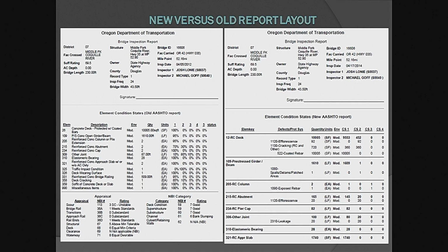So they're going to quantify for that 1 foot section a crack, and we're using that 1 foot because that's what the AASHTO and the feds have decided is you do it per unit. So in that 1 foot, we'll say there's 1 crack. Now they'll go along and they say, okay, I've got another 15 feet of cracks along all the other girders. So you'll quantify and you'll say, okay, I had a total of, let's say, 15 feet of cracking. That's how they're going to quantify. That's how they come up with the number.